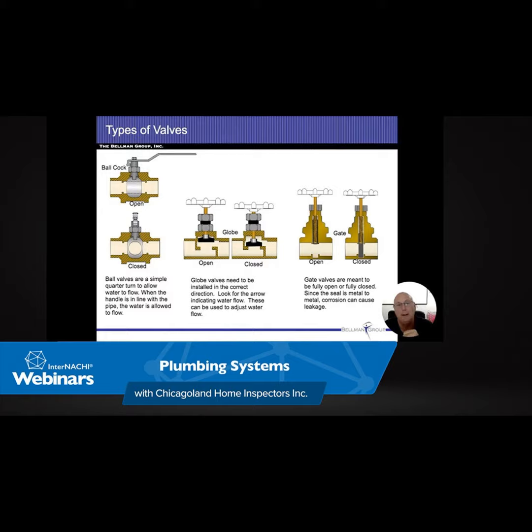If I didn't have any air and the pump was running, the pump would shut off after about 2 seconds because it would increase the pressure instantly. And then when the water was turned on, it would drop instantly. And now the pump is the only thing that's kicking on. We're going to feel that in the water: it'll get strong, weak, strong, weak. It'll be kind of weird when it runs. So we want to have air inside the tank. That's going to be our bumper, and that's going to keep everything nice and even.